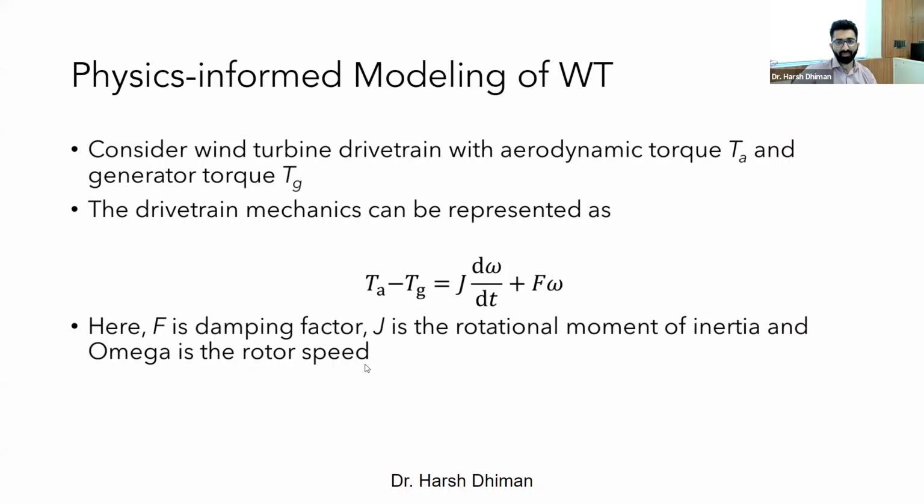So this is physics informed modeling. You can consider this modeling for the gearbox part, where you have your aerodynamic torque that is concerned with the incoming wind speed, and then there is generator torque that is associated with the generator. The interaction of both these torques is impacting your entire gearbox operation. So yes, there's a set of differential equations that governs the drivetrain, right?